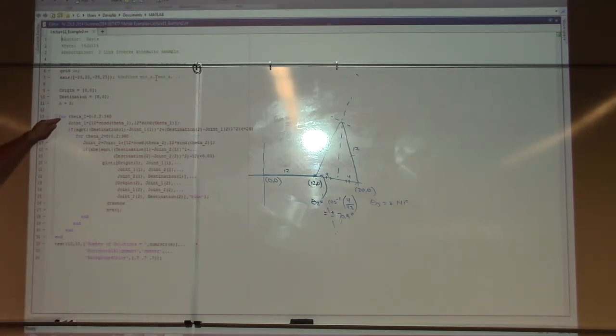The first loop is moving joint 1 between 0 and 360 degrees in increments of 0.2 degrees. Okay. I could go through and increment this in 1.8 degrees as I had previously advertised, and that would be more appropriate for a lot of the stuff that we do, just because of the characteristics of the stepper.